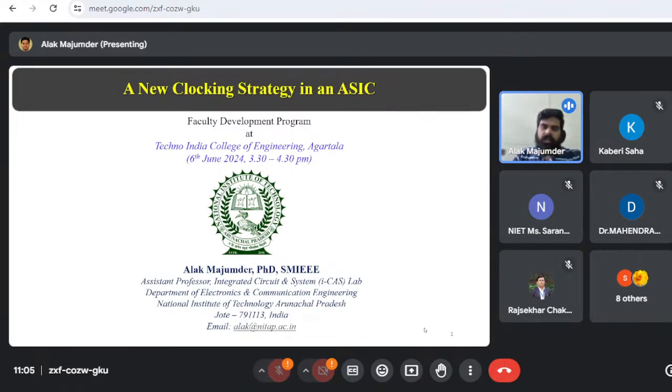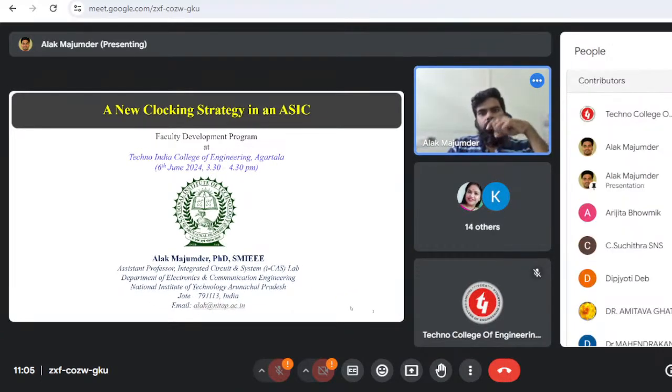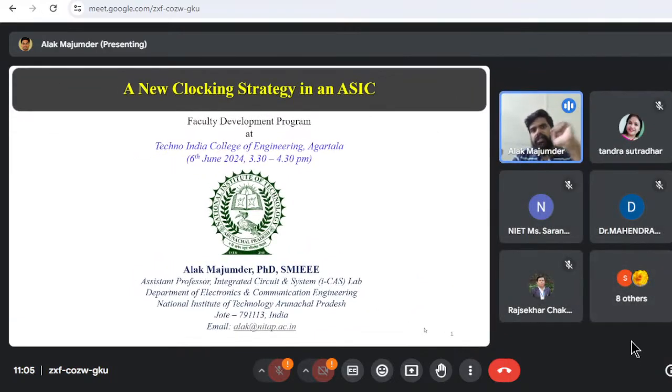So, in the morning session, we talked about a method called power gating, which is also important for the low power technology as well as for the reduction of the supply noise, which we have seen. When we discussed there, if you can recall, we discussed a terminology called clock gating, right? So clock gating can be incorporated in a system where clock is needed.